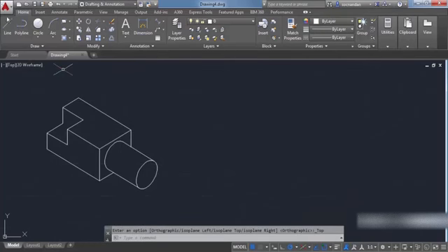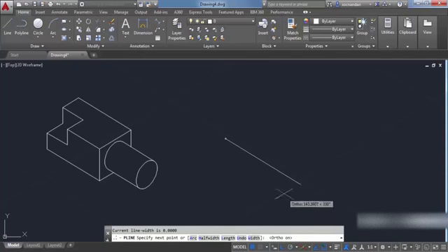and start with polyline command. So click on polyline and click at a random point to start making this drawing. When I start making this drawing, you'll see that a tracking vector now appears, which is with respect to the isoplane which we have selected. Right now this vertical tracking vector represents y-axis, and you can also turn this ortho mode on, and now we'll be able to make lines only in horizontal or vertical direction.